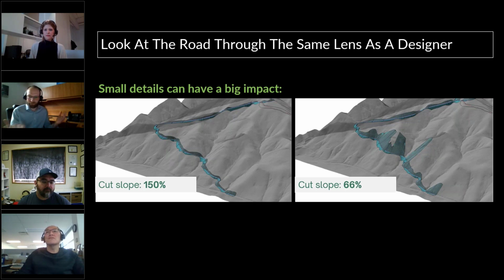So from a planning perspective, and that is our focus here, not necessarily the individual prescriptions that we can use to get around that, it would be: these hills look like they're maybe standing close to their angle of repose. If I cut into that, I'm going to expect to have to excavate a lot of material, so I would try and avoid that. I'd try and favor the gentle ground and explore other routes. It may be exploring other routes at a micro level, but it could be drastically other routes where we come from a different valley or ridge. Hopefully that answers your question.